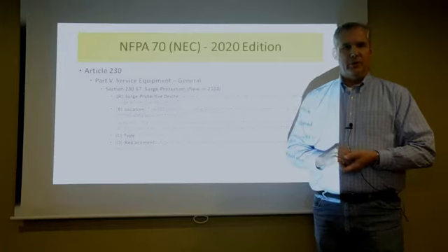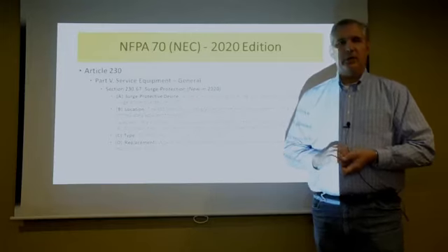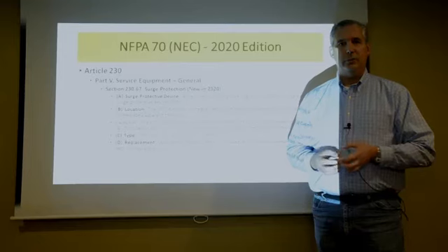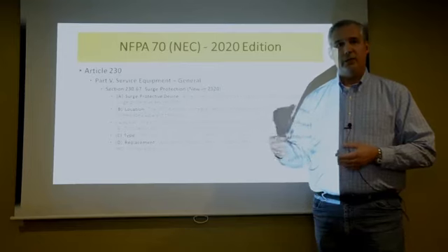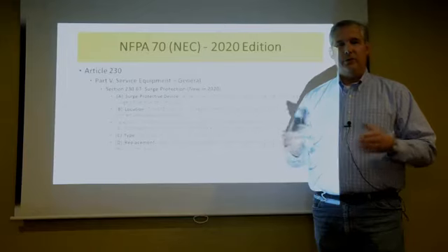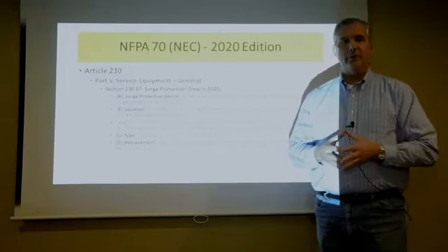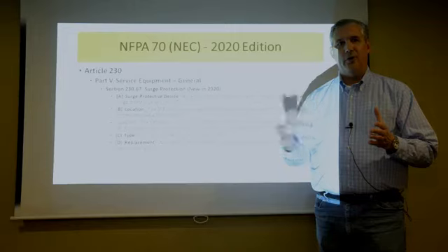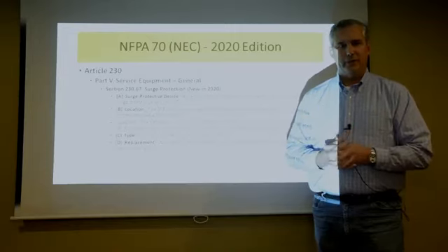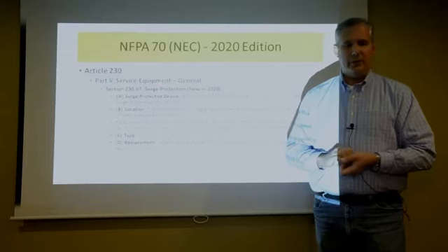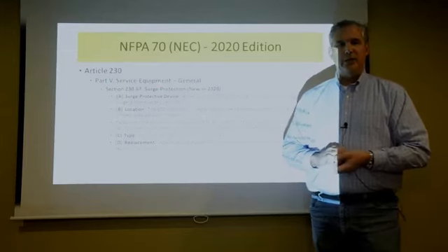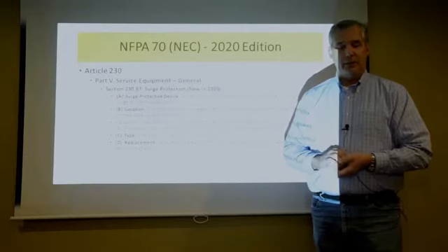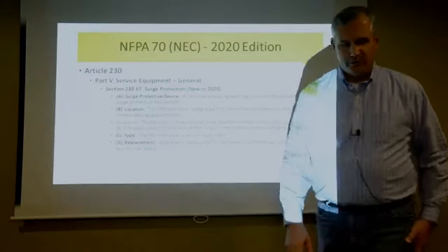This has become a safety issue over the years because smoke detectors, ground fault circuit interrupters primarily, are affected by surge, and surges will deteriorate those devices, and because they're life-saving devices, the National Electrical Code has put this in to protect not only the whole house, but those life-saving devices, the ground fault circuit interrupters, the smoke alarms, CO detectors, etc. So any new installations or upgrades to existing installations will require whole house surge protectors. And this is a testament to the importance of surge protection.